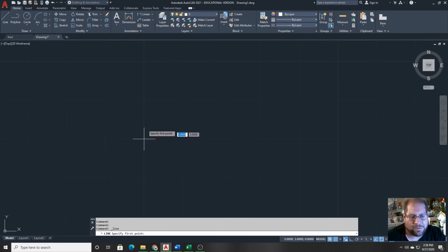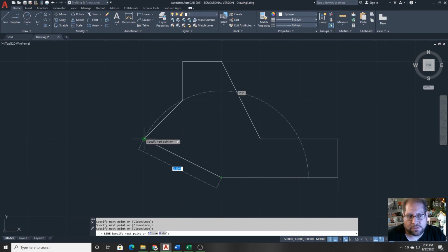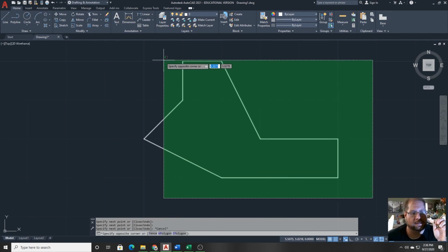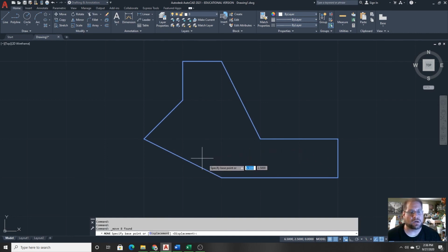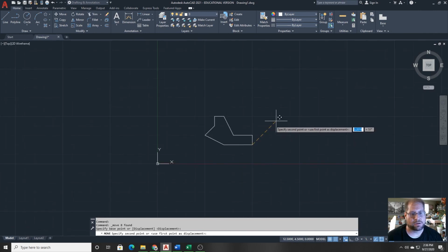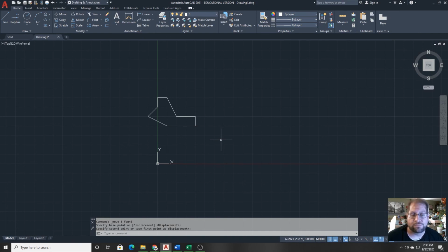And with that, very powerfully, I can go ahead and draw lines that fit on the grid, or I can move things as well with respect to the grid. So after I draw this irregular object right here, I'll hit escape, and then I could select all of it and hit move. And then when hitting move, I could simply click off the object or click on the object and move it with respect to those grid spaces. So it's pretty convenient to have the grid spacing set to what you want it to be, and certainly a matter of practice if you want to move it and change it as much as you like during the drawing.